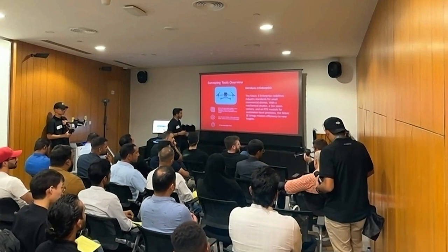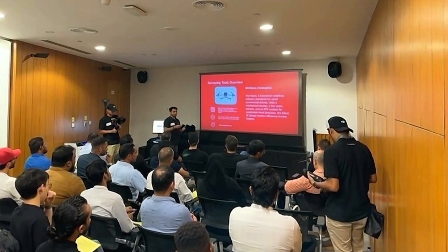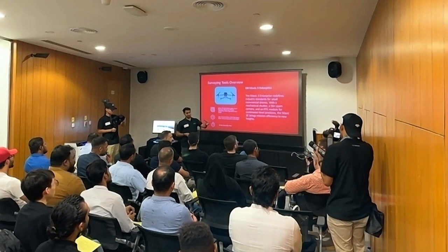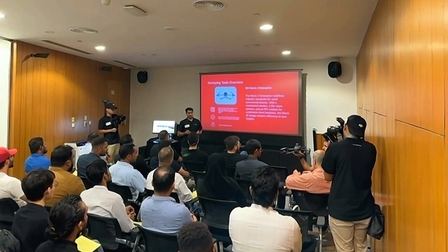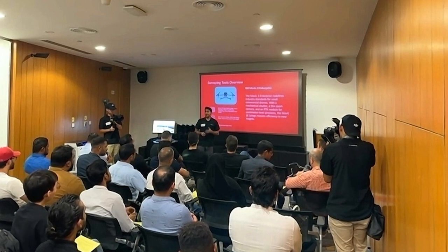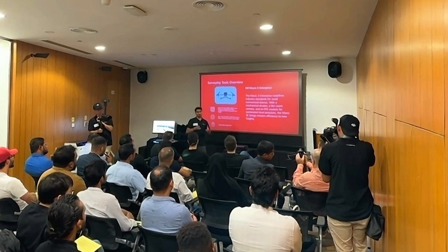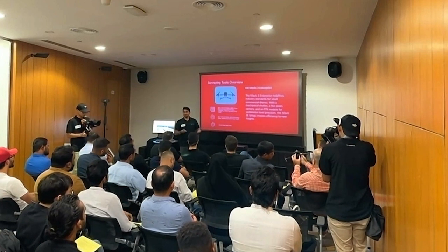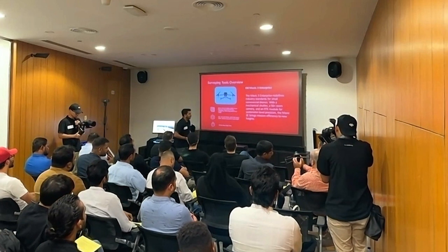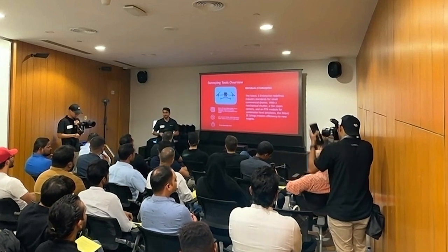And speaking of the accuracy of the data, using the RTK module on top of the drone, you are expecting accuracy of 1.5 centimeter in vertical and 1 centimeter in horizontal. Which means with the small drone, you can make survey grade accuracy possible. We will be showing how the drone works later in our workshop.